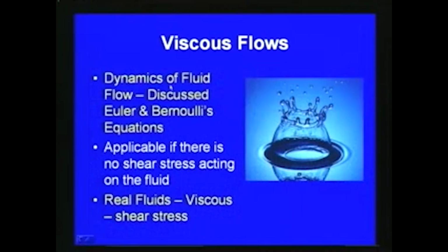Now, as I mentioned, most real fluid flows are viscous, so we have to consider the shear stress. In the dynamics of fluid flow which we considered earlier, we derived the Euler equations and Bernoulli's equation. There we neglected the effect of viscosity, so the derivations of the equations are much simpler and solutions can easily be obtained.